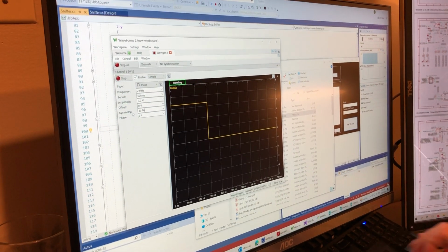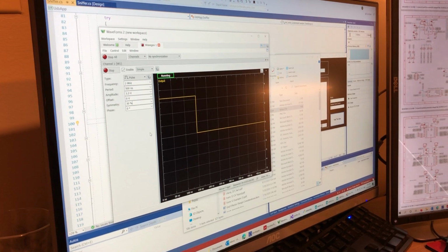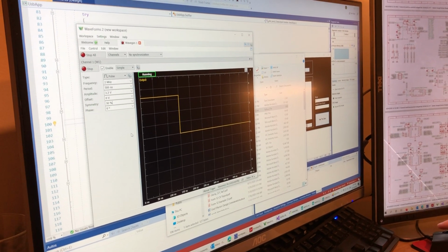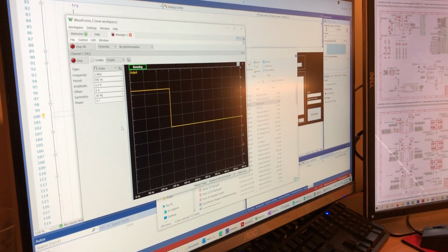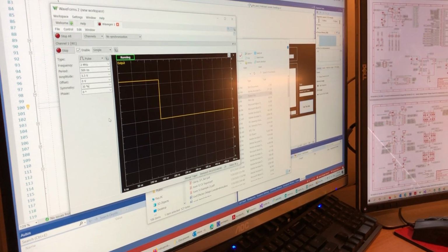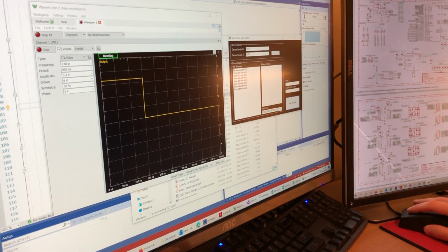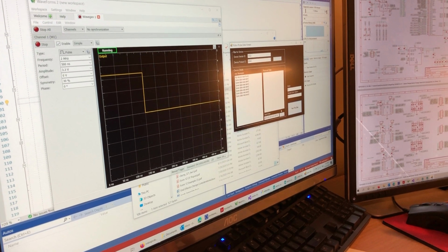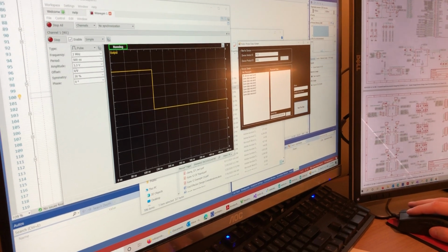It is worth noting that when you make the duty cycle on a 2 megahertz function less than 50%, what you really have is a digital waveform that's faster than 2 megahertz. So there is some error associated with these alternate duty cycles, but the overall period does match. Or wait, let's get this.